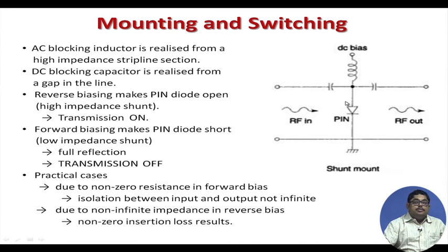So, that means, now please remember that in the other case, when high impedance is there, at this point the total voltage wave will be, because the reflection coefficient of an open is +1, twice the maximum voltage.